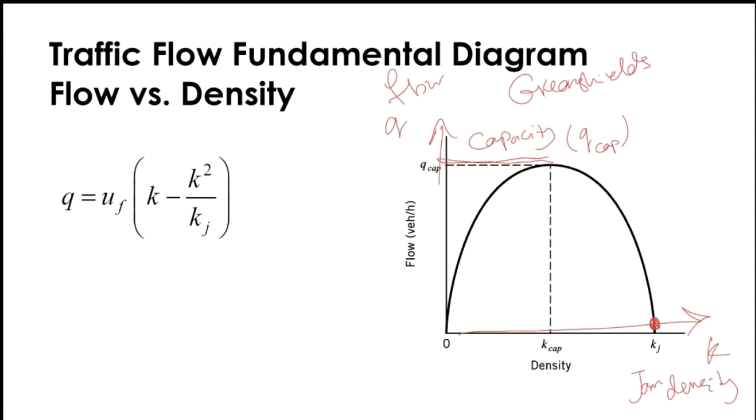And in the Greenshields model, one interesting property is that you see this Kj, and this is maximum flow. So maximum flow happens at a density that is associated with the capacity. So this K cap can be called density associated to the capacity, right? So at what density we'll have maximum flow, or at what density we can reach capacity.